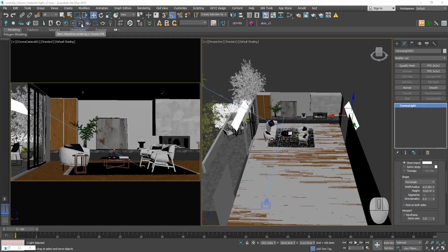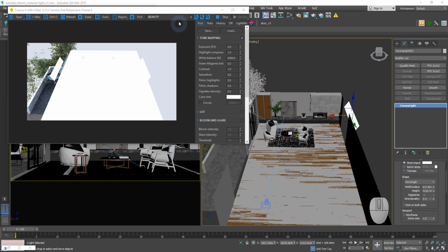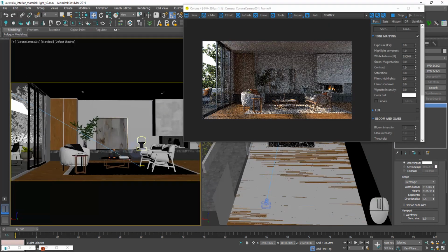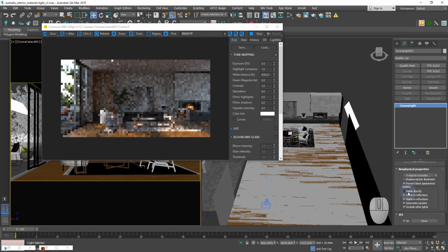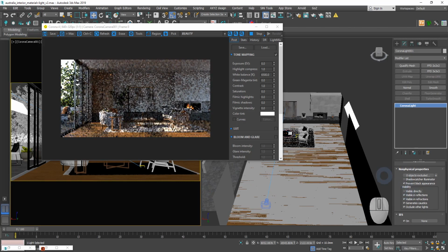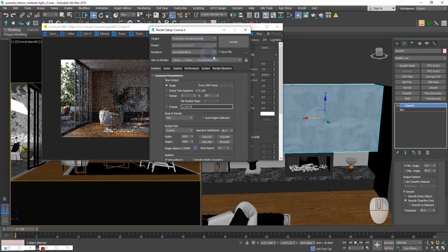And launch Interactive Render. In order to render the window, we need to choose the desired projection. We select the light sources and turn off Visible Directly parameter. In order for our render not to bounce between two projections, we select the projection with camera and lock it.